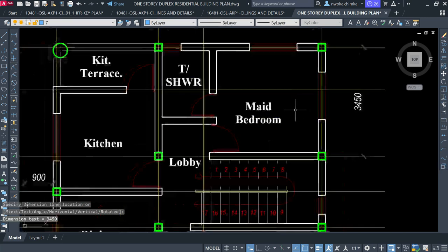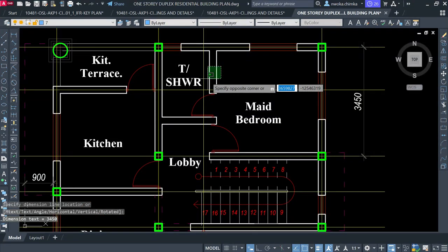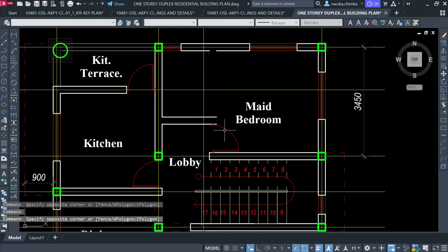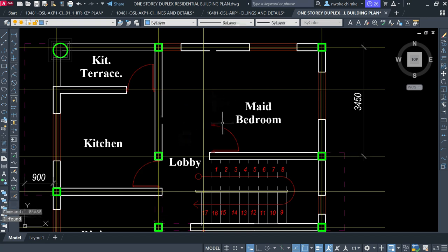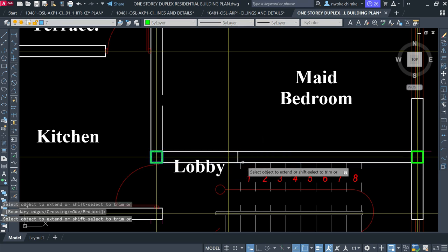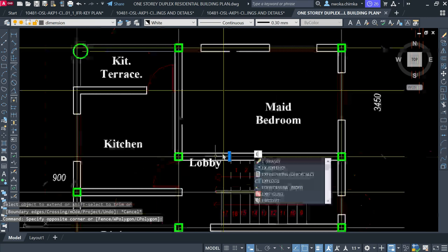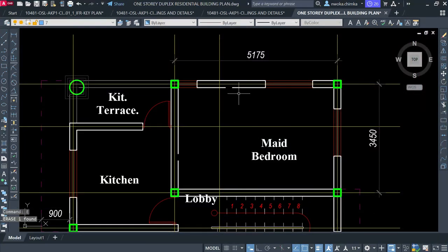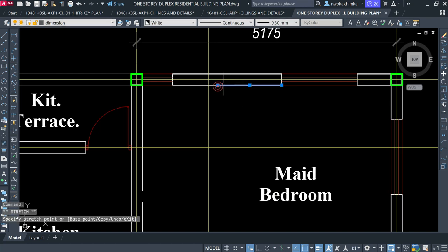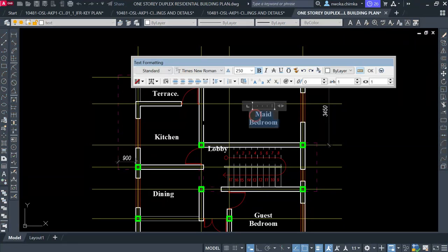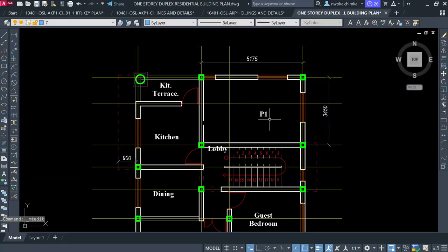So with this, I can choose to remove this toilet wall or beam, because I want to make here one panel. I'll remove this door, and extend my beam line, which is from this staircase. Extend this and remove this line. I can choose to join this one here. So basically I have gotten my first panel, so I can call this panel 1, P1.